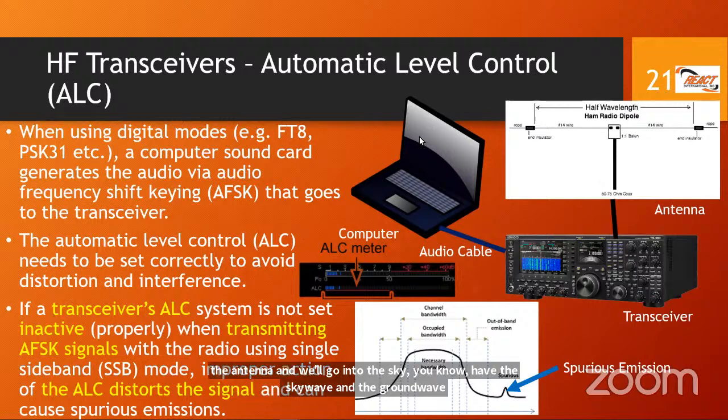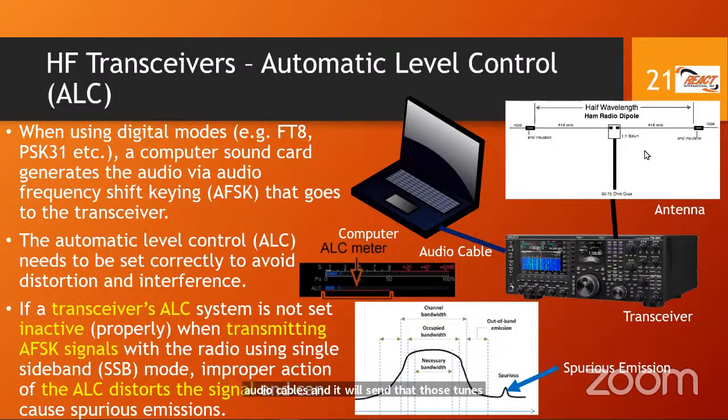But in digital modes such as FT8, RTTY, PSK31, JT65, those digital modes, the computer is doing the talking for us, right? It will generate the audio tones, and via this cable connected to the radio, it could be a USB cable, it could also be audio cables, and it will send those tones, and the radio will dutifully transmit it for us. And of course, vice versa. When we receive, the radio will receive those tones and send it to our computer, and the computer will interpret it via the software. So the radio sends the audio back to the computer, and that's digital mode operation. We're not speaking, we're using the computer to do the talking.